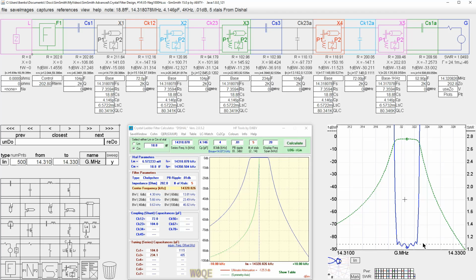And when we do that, we see the passband SWR came up a little bit, not much. Above the dotted line was basically the passband minimum before, which was 1.09 to 1. It came up a little bit, but it looks very, very good. So this did not hurt us very much in the design at all, by having this frequency need to be raised by an additional kilohertz.